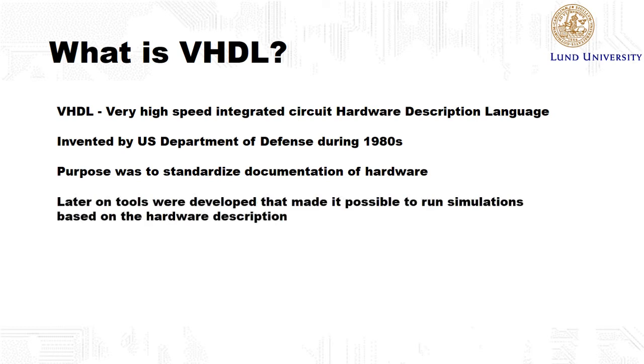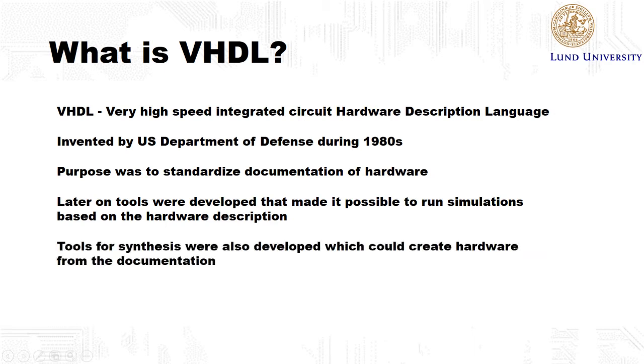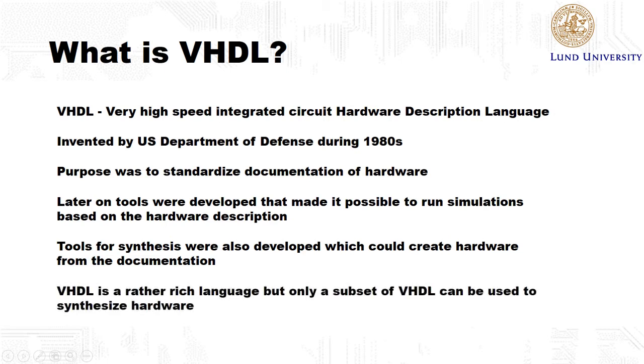Later on, tools were developed that made it possible to run simulations out of these descriptions, so people could actually simulate designs before they were manufactured. And a bit after that, tools for synthesis were also developed, which could create hardware from the documentation. Now VHDL is a rather rich language, but only a small subset of VHDL can be used to synthesize hardware, so keep this in mind if you find some code online.